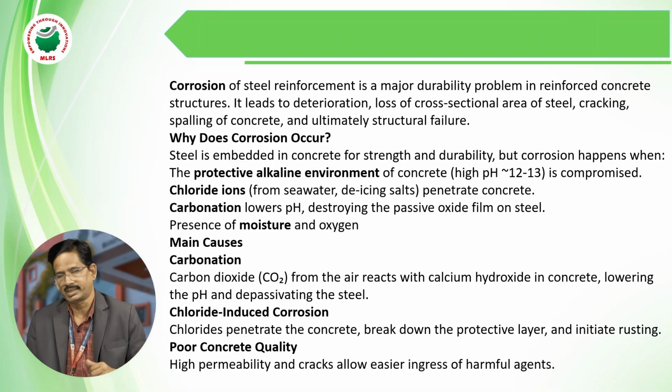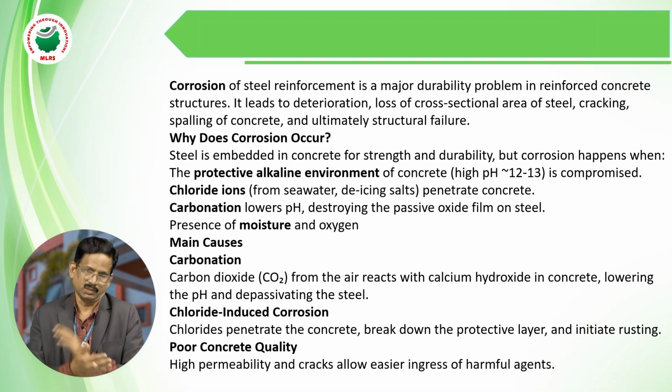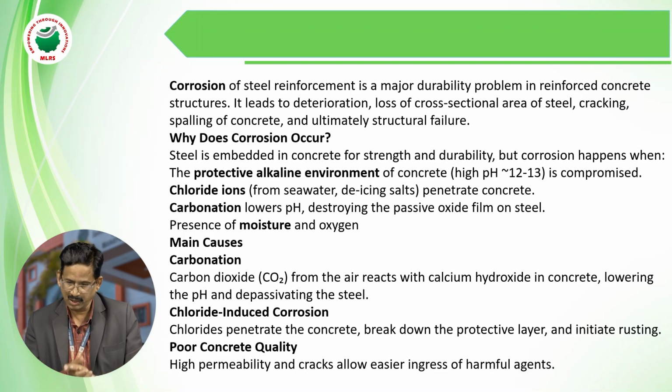Why does corrosion occur? Suppose I take a column. In the column, we provide the reinforcement in two ways: one is the main bars, and the other is the distribution bars. So, we provide the reinforcement in the concrete. If the concrete is exposed to the atmosphere, what happens? Oxygen will enter and reach the steel reinforcement, and corrosion will occur. Due to the corrosion, the strength of the bar will be reduced.